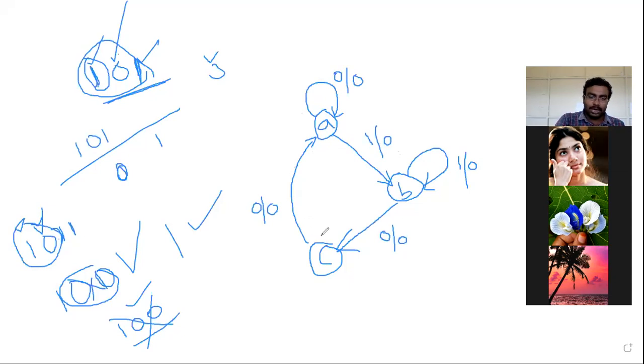That is one case. Now 10 is found using state A and B, and state C, if it is finding 1, tell me, students, whether your sequence is completed or not. Completed, sir. So what will happen if state C finds a bit of information 1? Your entire desired sequence 101 is completed and found, and it can generate an output 1 here. The job of the 3 states A, B, C is completely over, and you can end that sequence 101.